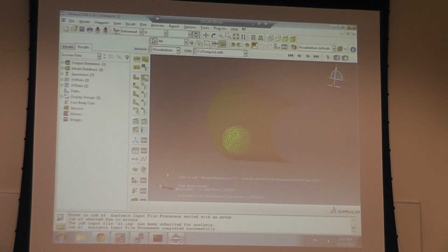now I chose to apply this as a displacement because I have more control over displacement. Everything will be more stable when I apply displacement rather than applying a force. If I apply a force on a ball that's in space, it's never going to solve, because there's no reaction to it. I'll never achieve static equilibrium. So I chose just to move it down with displacement.